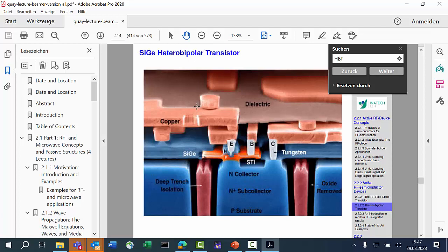So you see that this collector is only overlapping with this part because this goes to the back. So it's only overlapping for this small area. If it was in parallel, they would build extremely high additional capacitors, which would reduce our speed or our gain. That's not good.